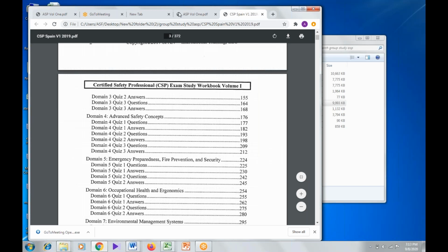So how to determine the process? Are you able to hear me? Yes. How to determine whether the process is covered under the RMP or PSM rule? Determine the quantity in the process and compare it to the threshold quantities. For example, a facility that uses a 1 ton chlorine cylinder would be covered by the OSHA PSM rule, but would not be covered by the EPA rule, because the OSHA threshold is 1500 pounds and the EPA threshold is 2500 pounds.